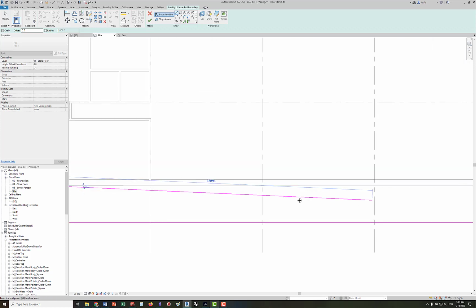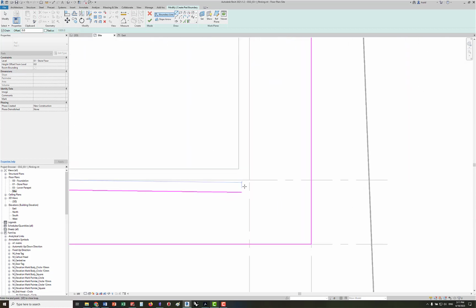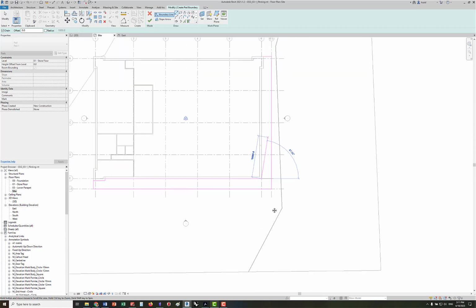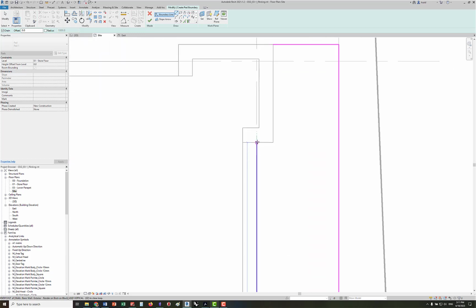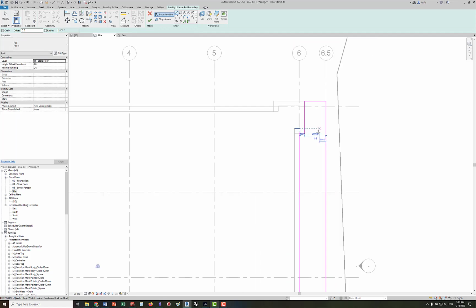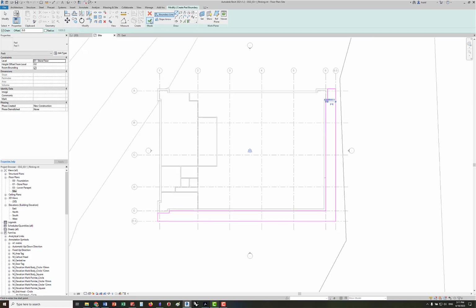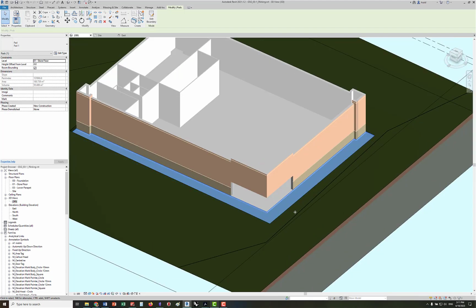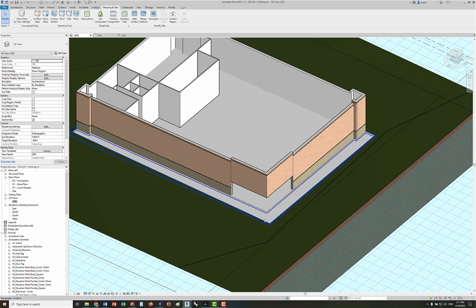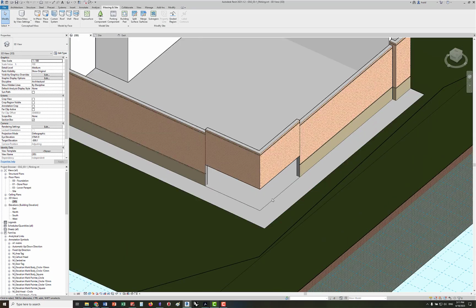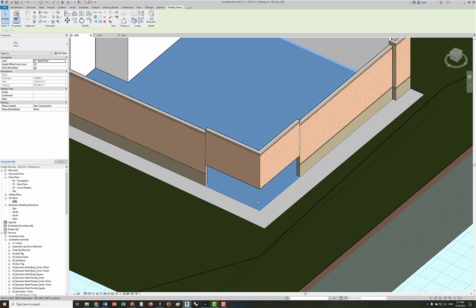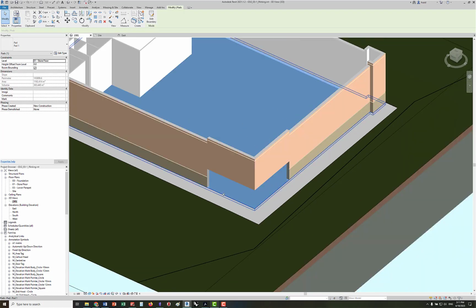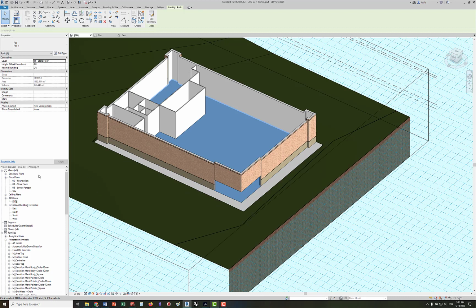Building pads have to have an enclosed region. So I will go back to the same point where I started. This is the sidewalk, and I say check mark, and if I see it in 3D, this is the sidewalk. The sidewalk is at level 0, so it matches the same level as the floor of the store. So that's good so far.